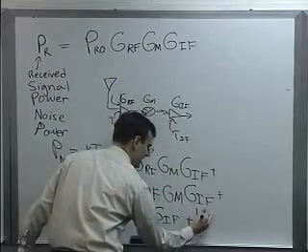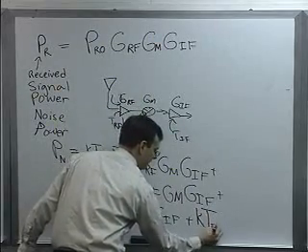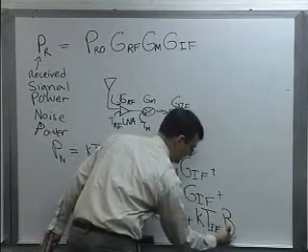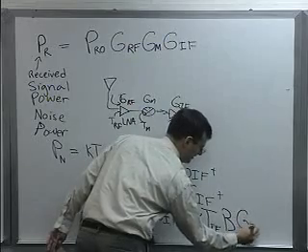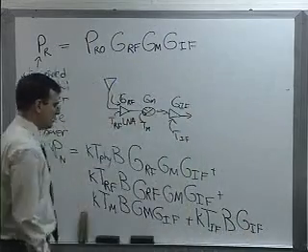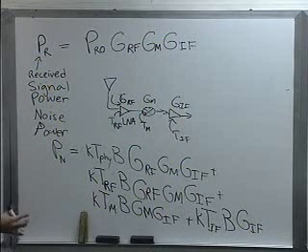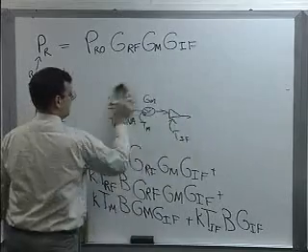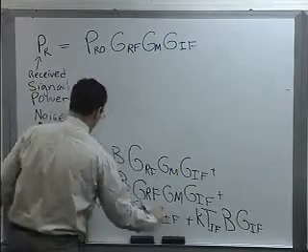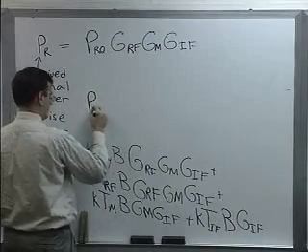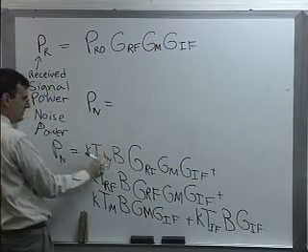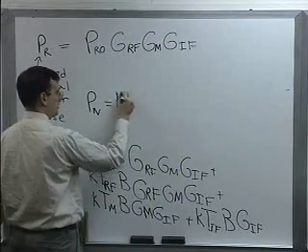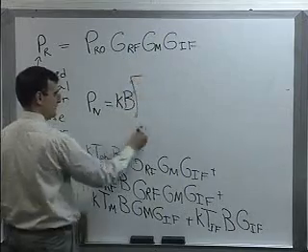So this is just going to be K T sub IF, the device noise in Kelvin, noise temperature for that device, times the bandwidth, times the IF gain. Well, as you can see in this treatment, there's a whole bunch of common terms. And we can just group them together. In fact, this is how we're going to group them. We're going to group them in a special way. P sub n. There's a K, a Boltzmann's constant, and a bandwidth commonality factor that's in every single one of these terms here.